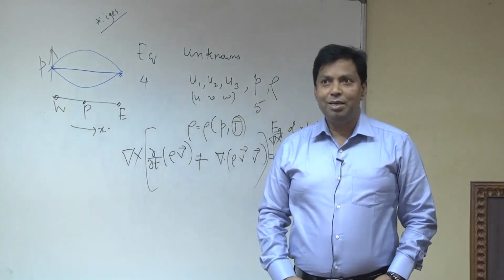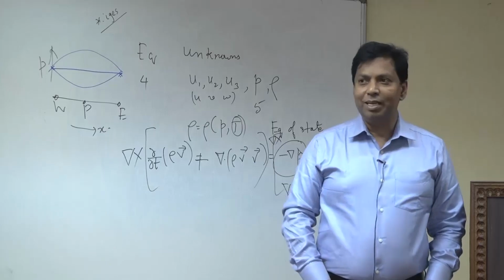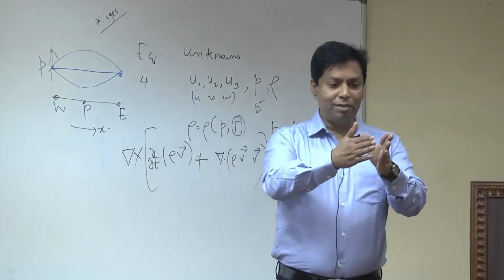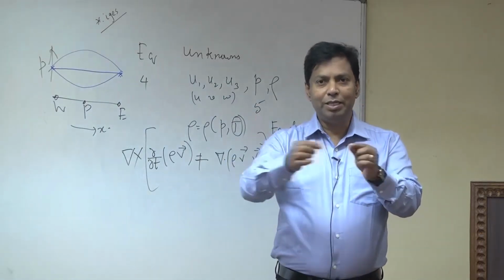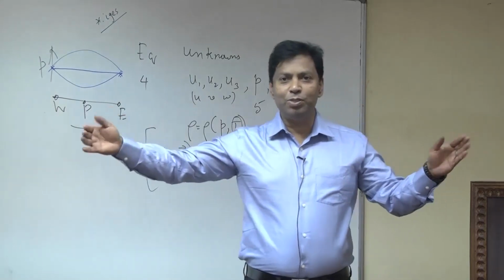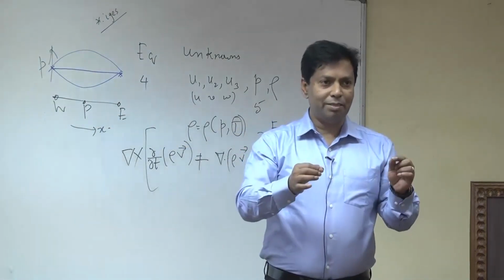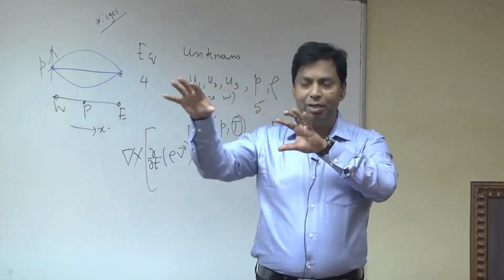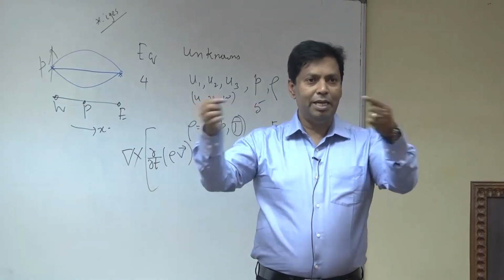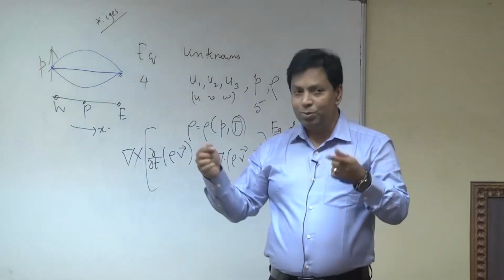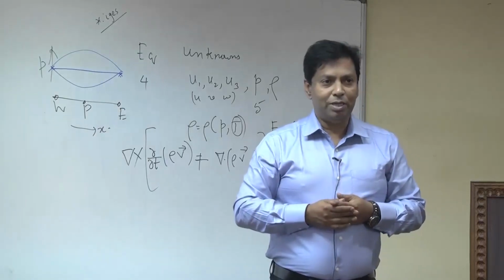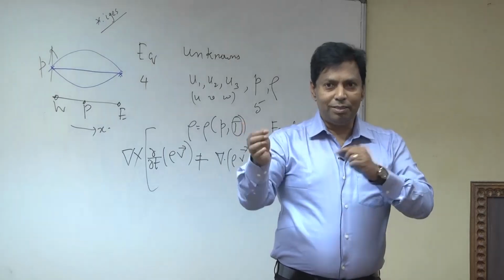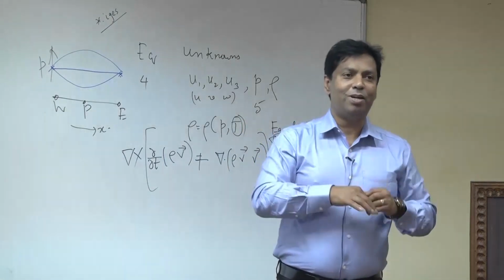You know, sometimes with parallel computing, if you use more processors, it will slow down because of what is called message passing. One processor will pass the message to the other one. So it takes some time. If you use more processors, it takes some time to pass the results, because of the domain decomposition. They are dividing the domain and solving one part on one processor, another part on another processor, and they are exchanging the values. To exchange the values, it takes some time. For example, maybe 4 processors is good for you, but if you use 8, it takes time for this message passing and it slows down your simulation.